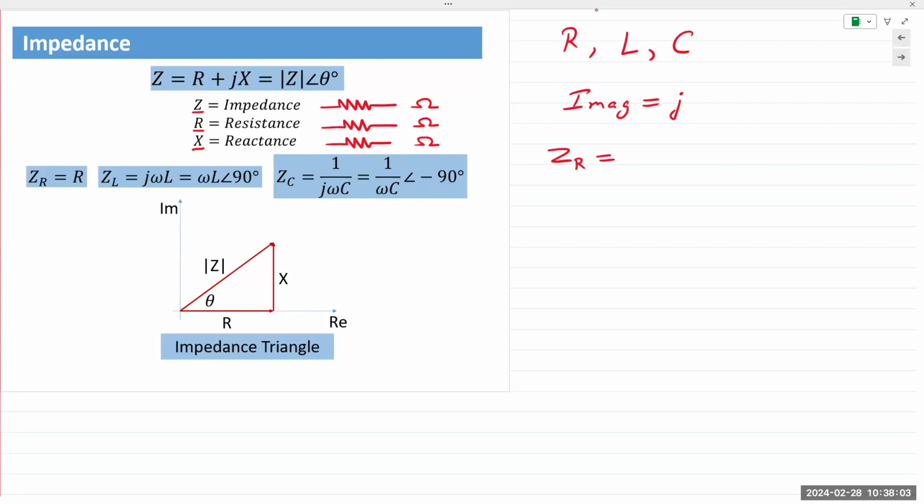It's the resistance itself, because it is R plus J0. There is no such thing as the impedance of a resistor separate from resistance, because it doesn't have any reactance. It's simply the resistor itself. Remember, a resistor behaves exactly the same way for DC as well as for AC. It simply opposes the flow of current and causes a voltage drop to appear across it.